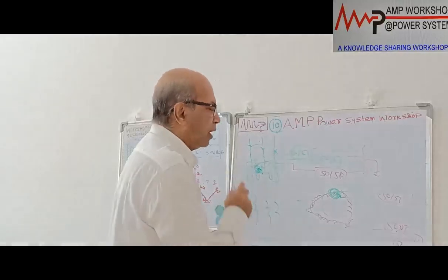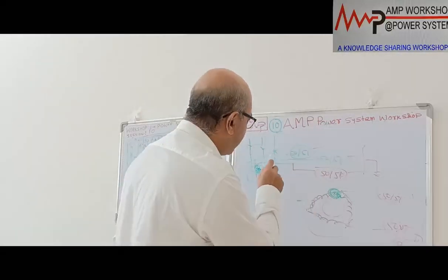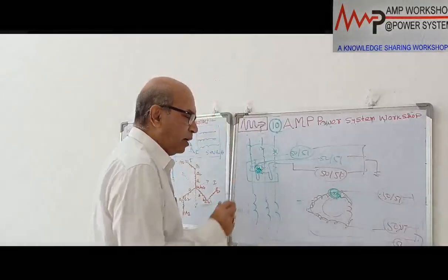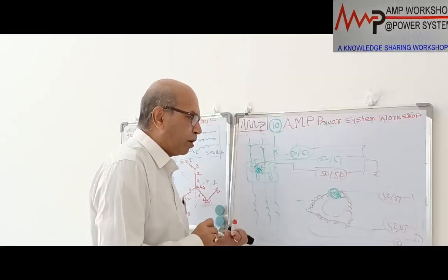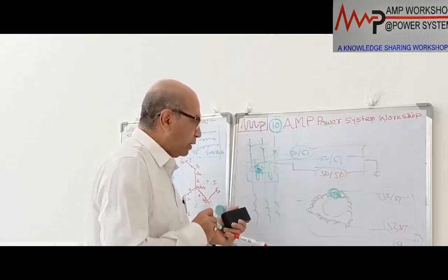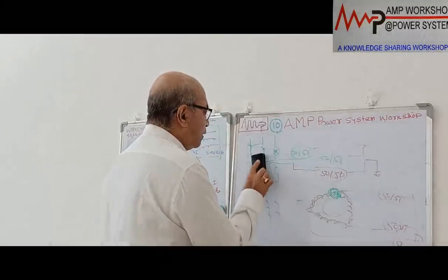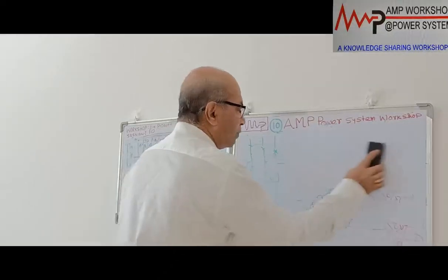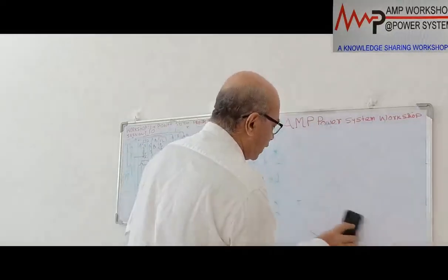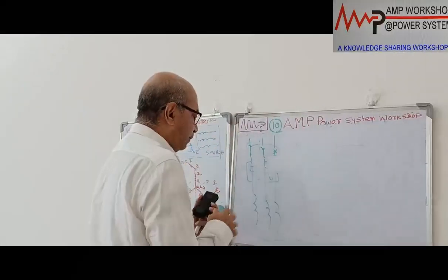So this is for external arc fault, and this is now for internal arc fault. What is the arrangement? There are 2 protections for the internal arc fault of this transformer that we provide. We put 2 sets of CT over here. This is 1 set of CT. Another set of CT we put is a summation CT. That is a residual connection we make over here.